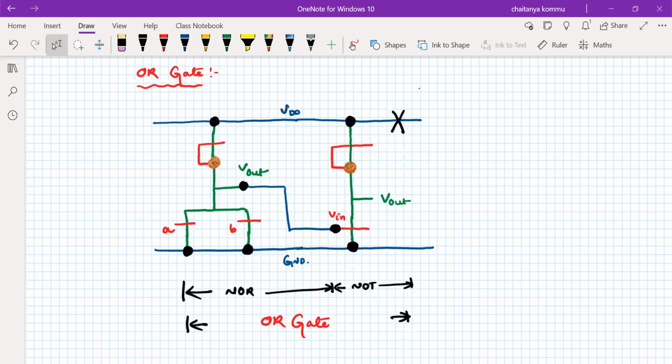Whatever circuit I give, for example AB plus C, the stick diagram can be drawn very easily. Please remember that once you know the stick diagram, only then is it possible to draw the layout. Without knowing the stick diagram, it is not possible to draw the layout diagram. You should learn this one. Otherwise, it's sometimes very difficult to learn the layout.